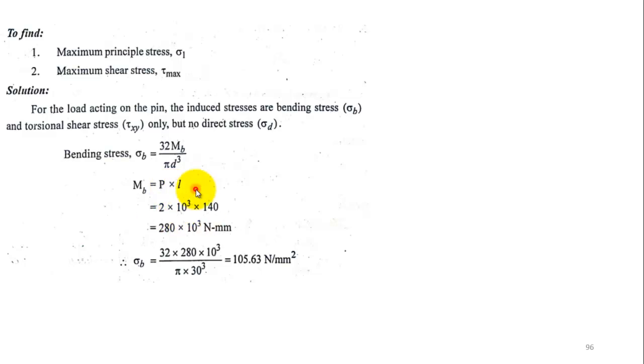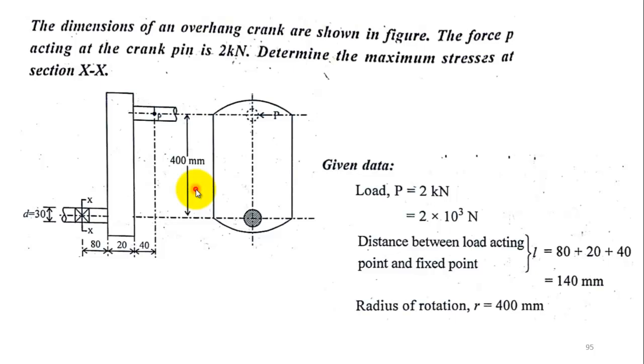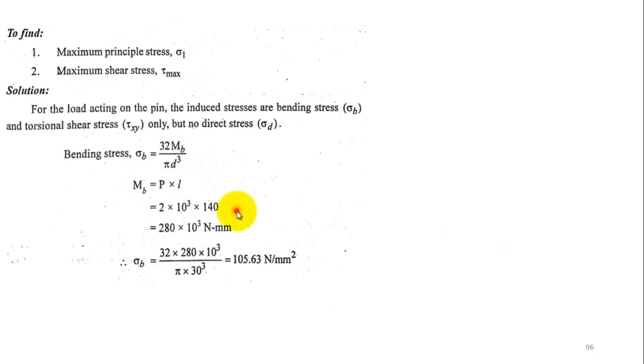Load they have given as 2 kilonewton. Similarly, L is given as 140 millimeter. You can calculate the bending moment, 280 into 10 power 3 Newton millimeter. You can substitute that bending moment value here and you can calculate the bending stress.